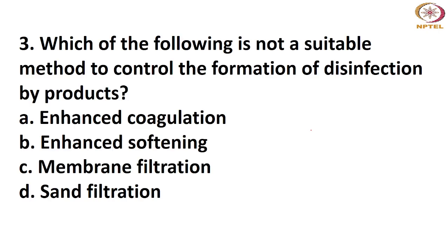So the correct answer is D. That is, the sand filtration is not suitable. In case of membrane filtration, we can remove all the disinfection byproducts. Enhanced softening and enhanced coagulation will also help.